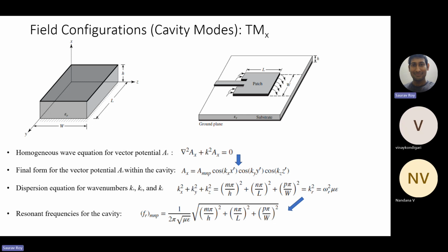It is reversed to sine, right? So cos: what happens at the beginning, at phase zero, it becomes maximum, and in the middle it has opposite phase. So it happens mainly because at the two ends of the metallic cavity we have zero voltage and maximum current. That is why this vector potential will also have this kind of cos variation.